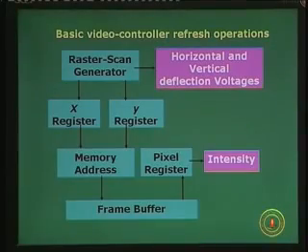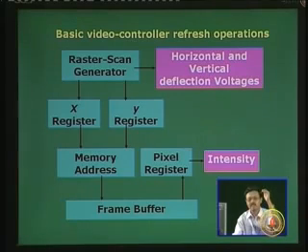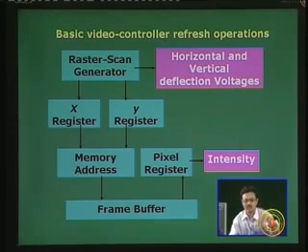Job of a video controller, it's very important. Remember from the previous diagram, if necessary we will revisit it again, it basically gets the input from the frame buffer and drives the monitor. What do you need to drive to the monitor? You need to give input to the monitor two things: where the beam should be and what should be the intensity of the beam. I repeat again, the beam is being scanned from left to right, each scan line from top to bottom, back again to the top, that's fine.